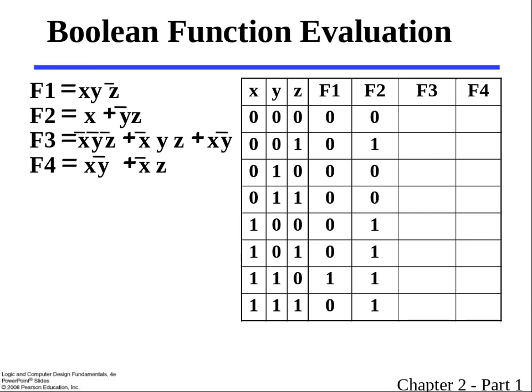If you're NOTing all the zeros, and then you're ANDing the NOT of zeros, what does it have to be? Well, NOT 0 is 1, NOT 0 is 1, NOT 0 is 1, 1 and 1 and 1 is 1. And then you're ORing other stuff, so the answer has to be 1.